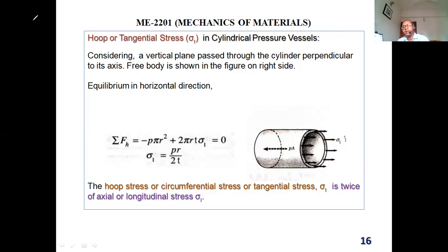That means it works like a spring, like this one. Right now, I cannot break it, right? But if I do it several times like that, it will break. That is called fatigue failure.